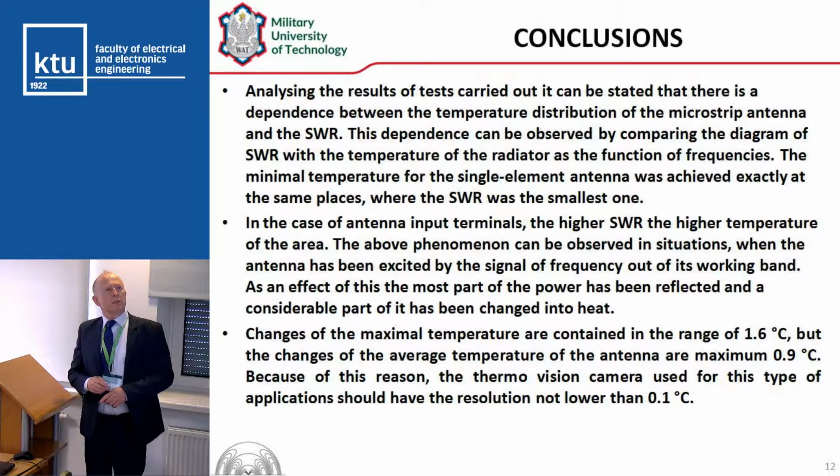The minimal temperature for the single element antenna was achieved exactly at the same place where the standing wave ratio was the smallest one. In the case of the antenna input terminal, the higher the standing wave ratio, the higher the temperature of the area.